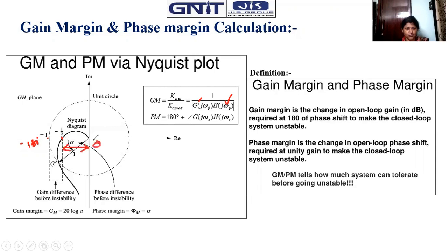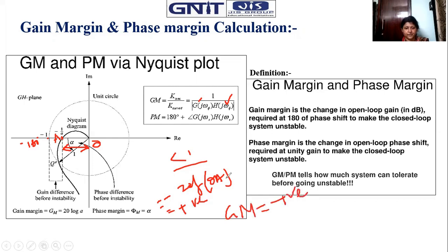First of all, you have the transfer function G(s)H(s), then you look at the open loop pole-zero map, from where you determine the value of P. Then just take the help of mapping, and you calculate the encirclement about the minus 1 + j0 point. What is the number of encirclements you are getting? Now put the values of P and N in the Nyquist stability equation, and you easily get the number of zeros existing, that is, Z means the closed loop poles existing in the system.